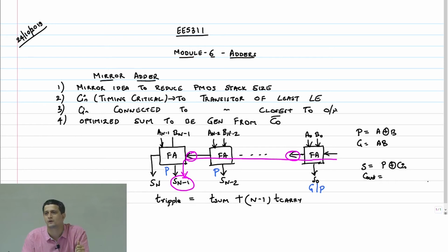What about carry out? Yes. Either the carry is going to be propagated, which is controlled by the signal P, or it will be generated. The delete you don't have to take care of, because delete is the case when both P and G are 0. Output will automatically be 0. So this is nothing but G plus P into C.